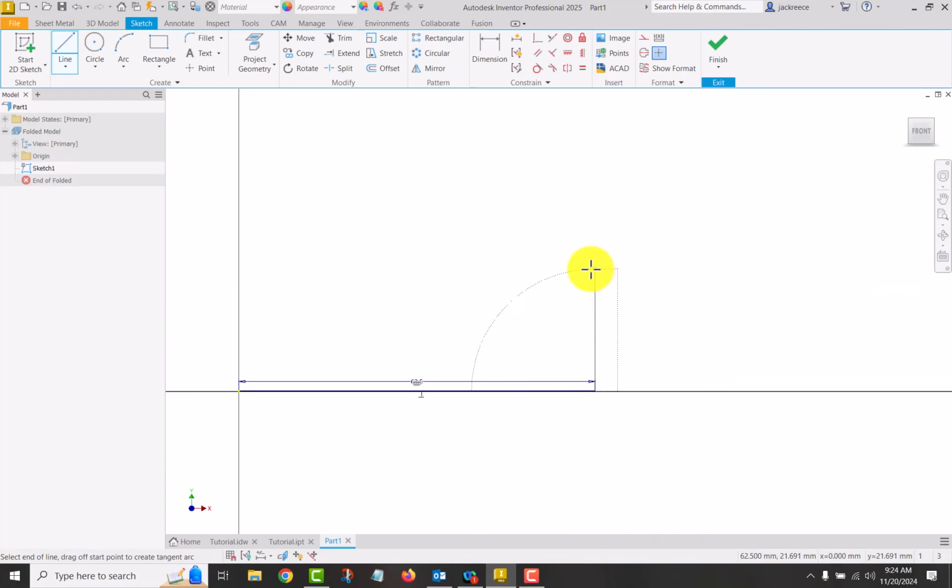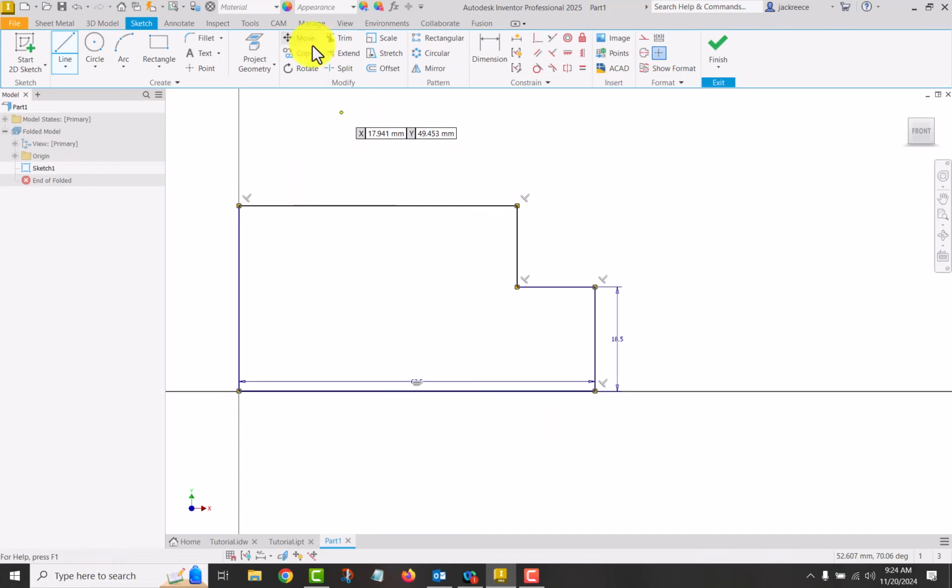And then we want to go vertical 18.5 millimeters. We're just going to come horizontal, go vertical again, come back over to the snap over the origin, and then down to close that off. Okay, and so we should have perpendicular constraints at all the corners.